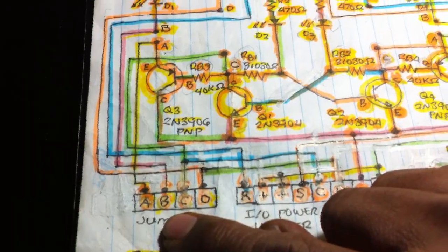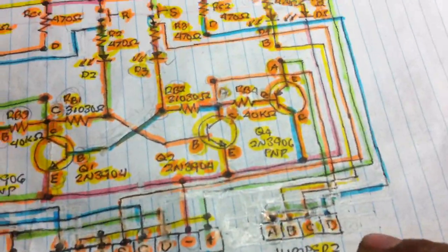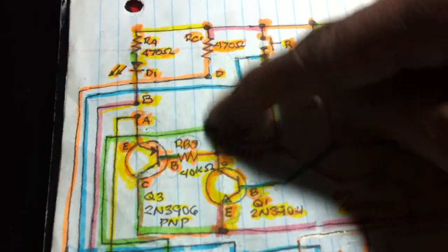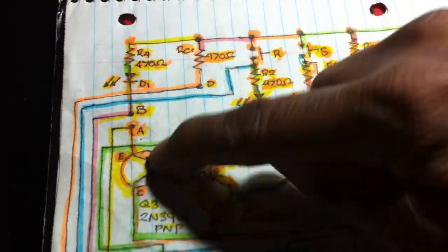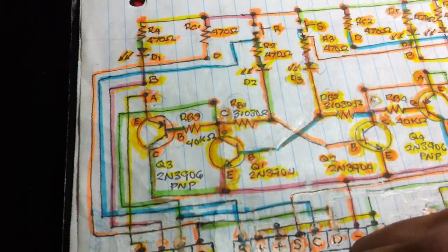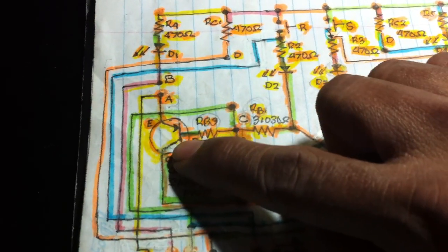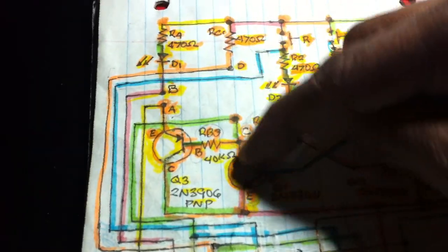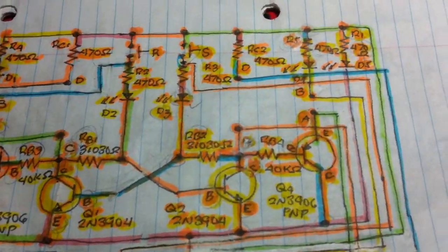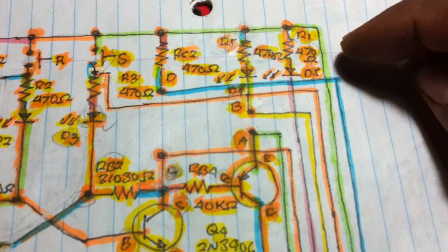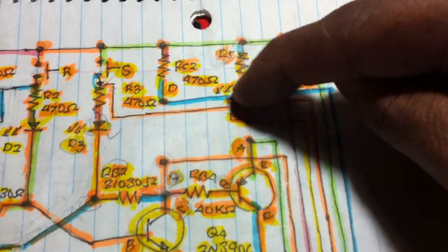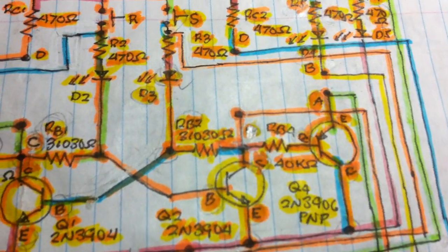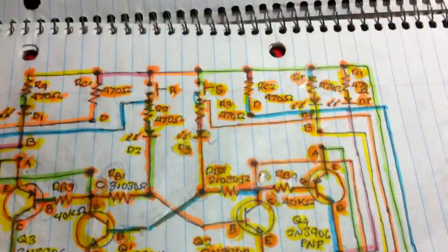schematic diagram using the power header, jumper. When I'm going to use it without PNP, I just slide the header connecting this line to here. Without this, just connect it by a header or by the jumper. Or if I'm going to use it with the PNP transistor, just slide the jumper here. We're going to connect here and here, same as the other side. If you plan to connect only the output, a simple bistable multivibrator, just connect this B to C through jumper settings. That's why.